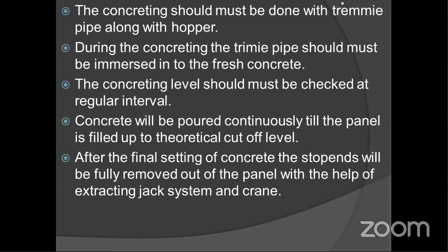While doing that concreting, we should lift our tremie pipe along with that, but we have to take the precaution that some portion of our tremie pipe must be inside the fresh concrete. This should be done by skilled supervision on a daily basis to ensure correct procedures and to carry out all the measures, and we have to record each and everything.